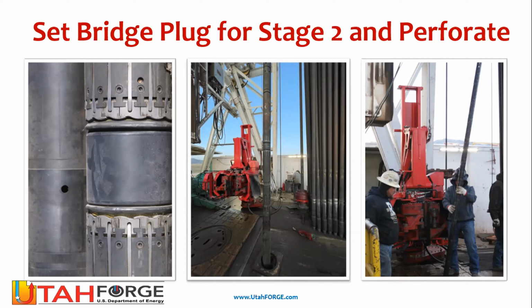We just wanted to simplify the fracture geometry that was created, and we ran a relatively long gun so that we could maximize our opportunity for finding initiation points associated with natural fractures. So isolated, perforated,